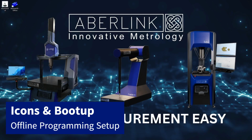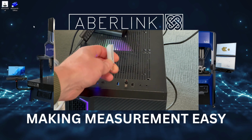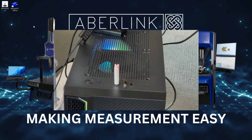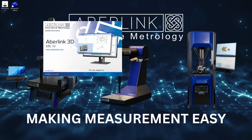Now the software is downloaded and installed, you should see the two Aberlink icons on your desktop. This is the white icon, Aberlink3D V4, and the blue icon, Aberlink3D Offline. It's important when programming offline to only use the blue icon. So make sure your key lock is plugged into your laptop or PC, otherwise the software will not allow you to take any points. And with the key lock plugged in, you are ready to then double click the blue offline icon to start up the software. The software will run through some checks and then open up full screen.